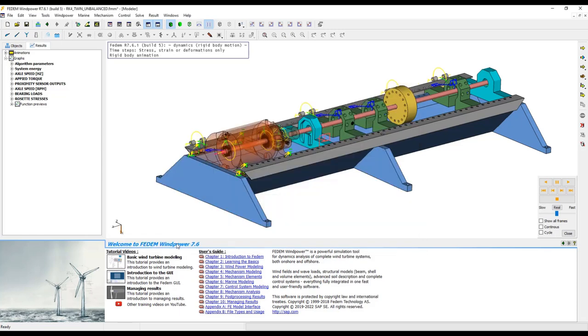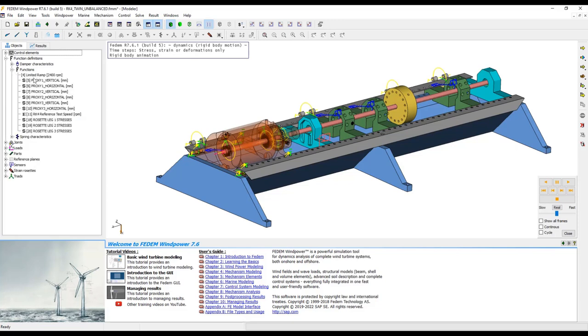However, there is one thing you have to remember, and you have to go to the functions, and in an FMU you have to predefine the inputs and outputs, and that's what you do here with the functions. Here, all the functions or the results which are tagged sensors are output from a FMU, and those who are marked external, which are those actuators used as inputs to the digital twin model.